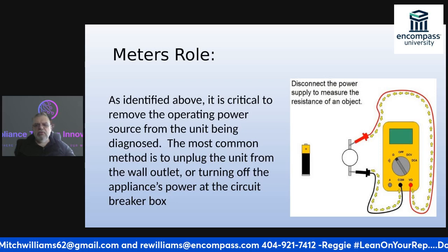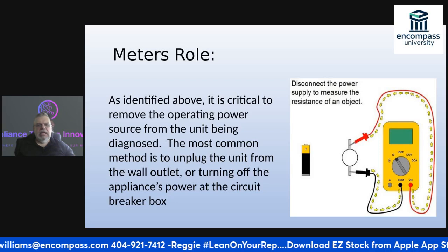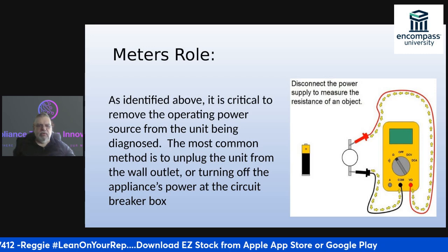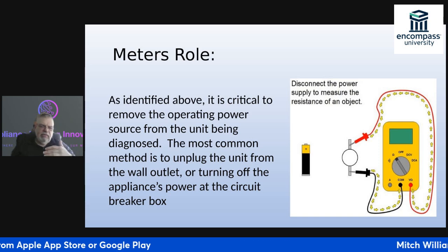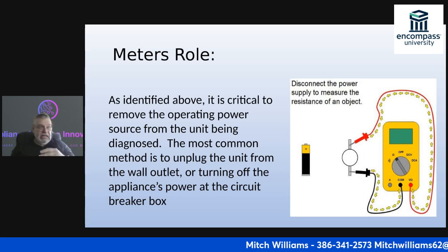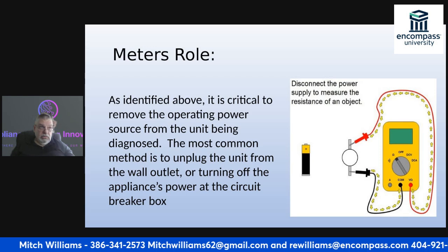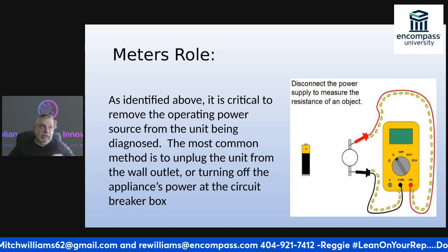So the meter's role is critical to remove the operating power source from the unit before being diagnosed. The first thing that I always tell everybody is, if I'm going to measure something that is not current related, whether that be amps or volts, I do not want the unit plugged in.